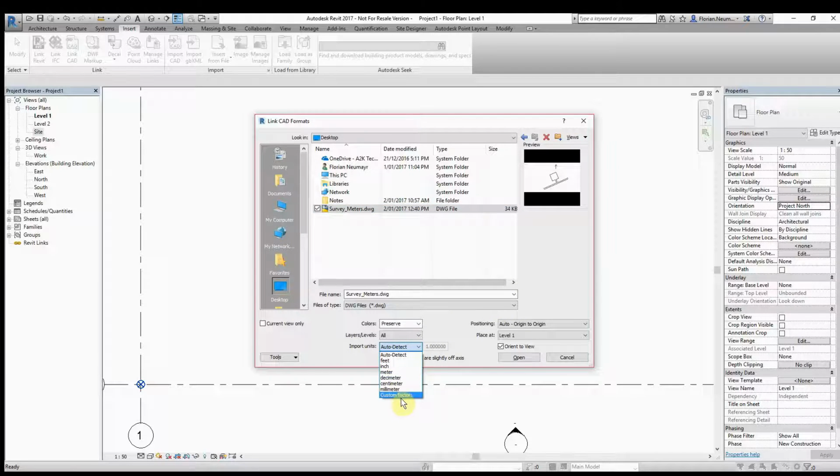Obviously it shall be in meters, which is good. If I know the coordinates, ideally always check and look up these coordinates beforehand. All right, good. So correct lines that are slightly off axis, this is meant because a survey is never straight. And we don't want this for this current view only, we want it for all views, so that I also see this in 3D.